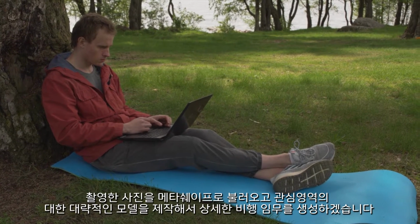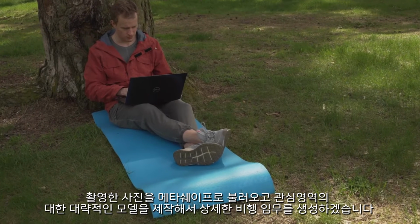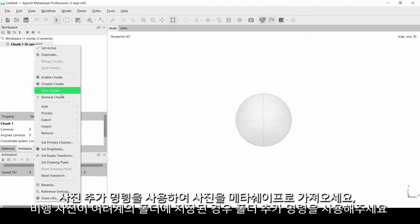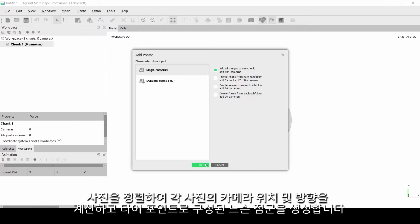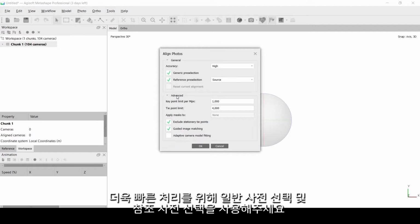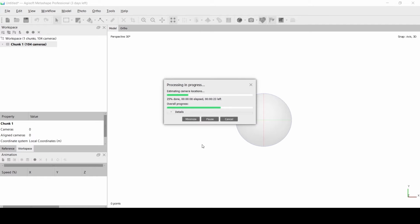Import captured photos into Metashape to build a rough model of the region of interest and generate a detailed flight mission. Import photos into Metashape using the Add Photos or Add Folder command, in case overhead flight imagery is stored in separate directories. Align photos to estimate camera position and orientation for each photo, and generate a sparse point cloud consisting of tie points. Use generic preselection and reference preselection source for faster processing.